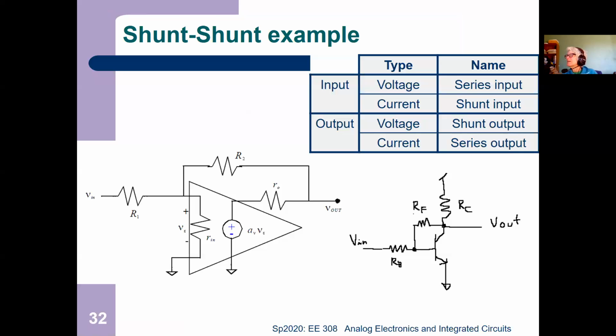amplifier. And what kind of amplifier is it then in terms of currents and voltages? And resistance. V over I, transresistance. Yes, exactly. So it's a current input. VN's contributing some current in, feedback's contributing some current, and that's what determines the voltage at this node. So it's actually current that's being fed back. VN is not setting this node directly. It's the current from VN and the current from the feedback that's setting that node.